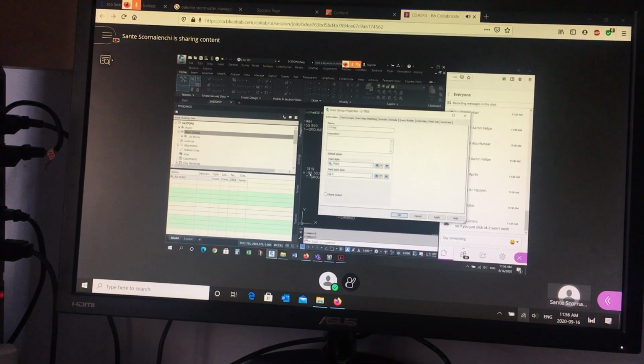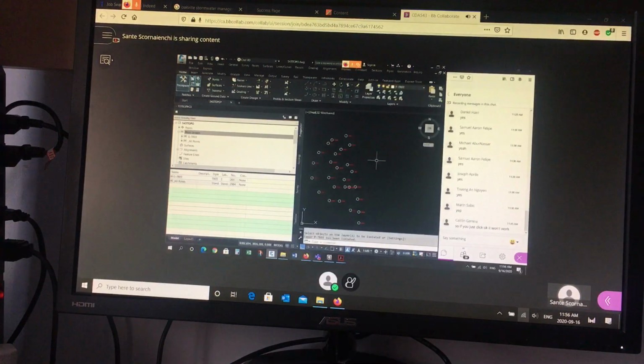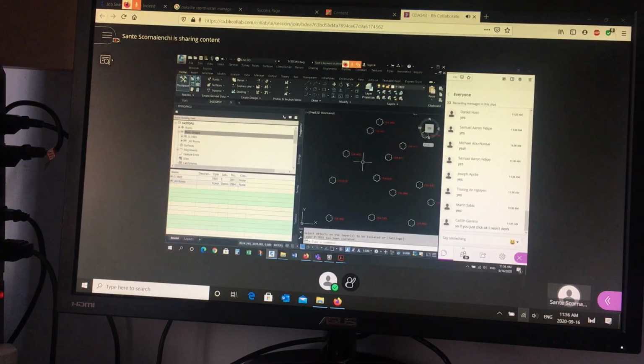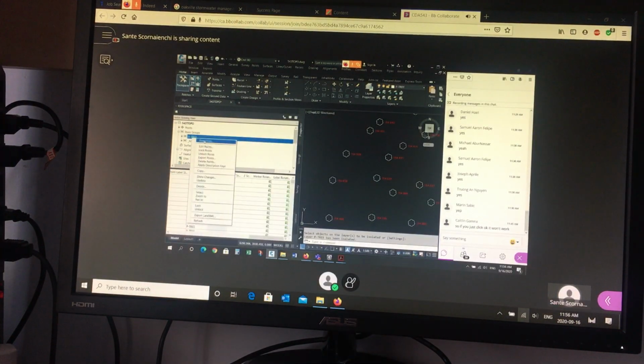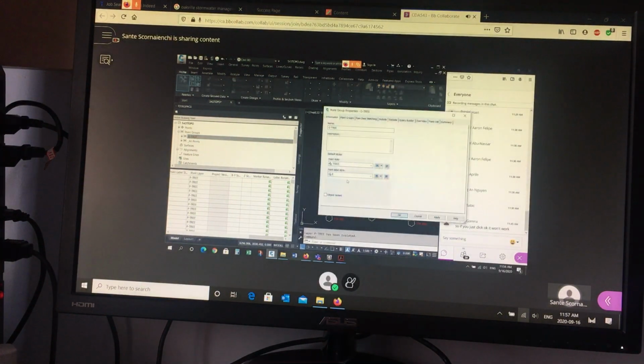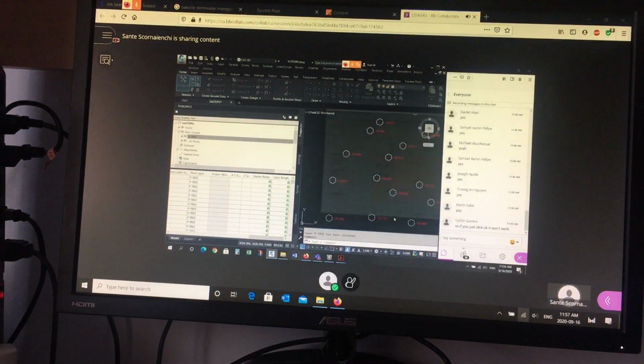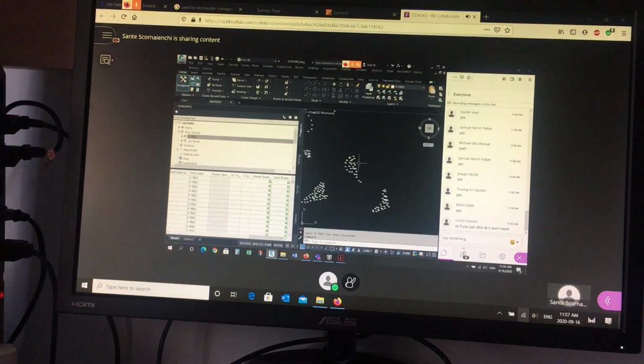If you remember the group, you can globally, en masse, change it. Say, oh, I want to see all three. Go back to the group properties and change it to the other. So I see number, elevation, description. That'll come up if I globally change them all. If you don't want to see the label, you can create a no display label, or you can actually apply no label. Just say none. Now you see just the trees. So you can see how you can globally change your settings for everything. So that's a very handy drafting tool.